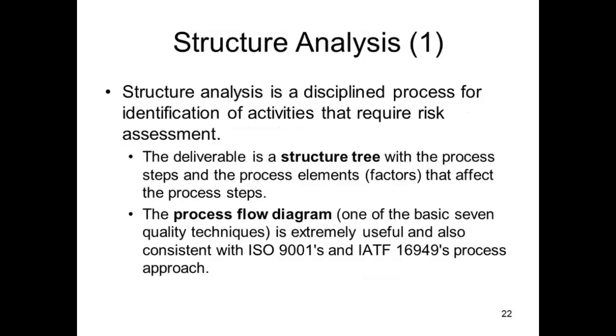So the next step is structure analysis. Now we'll get into the actual preparation of the FMEA. It's a disciplined process for identification of activities that require risk assessment, and the deliverable is a structure tree with the process steps, which pretty much come from the process flow chart, and the process elements, which are not necessarily part of the process flow chart, that affect the process steps. So essentially, structure analysis is very similar to the process flow diagram, but we're also going to add the process elements or factors that affect the process steps.